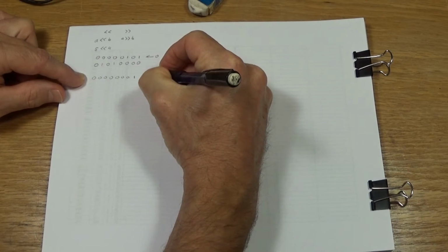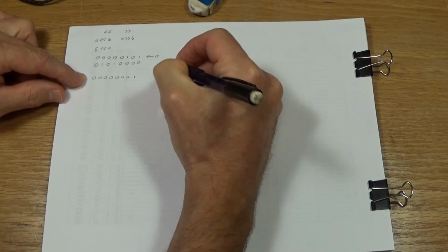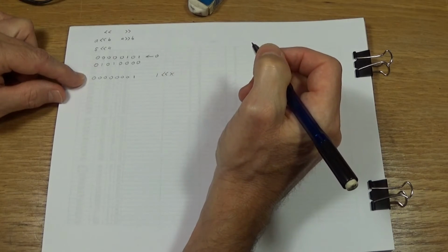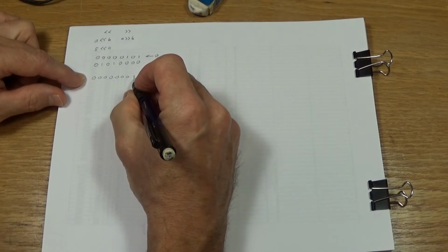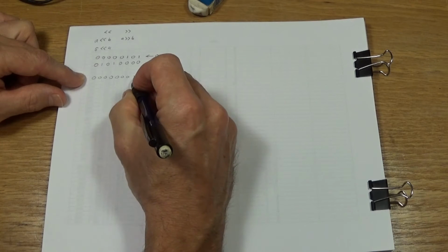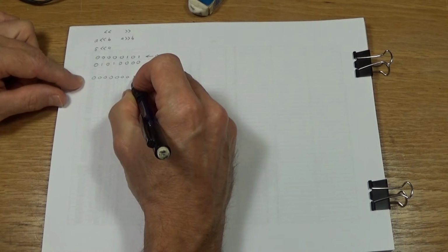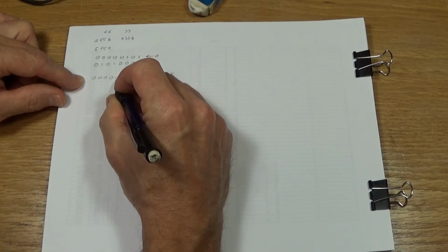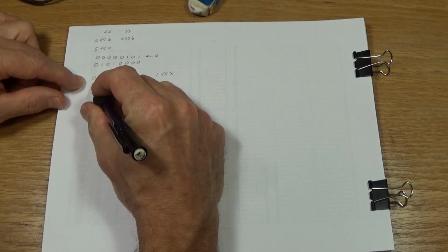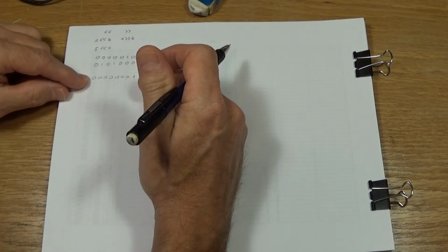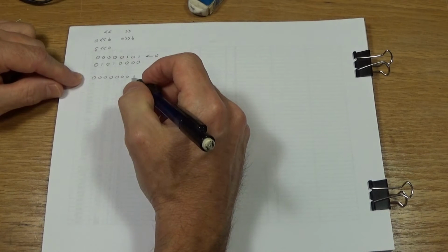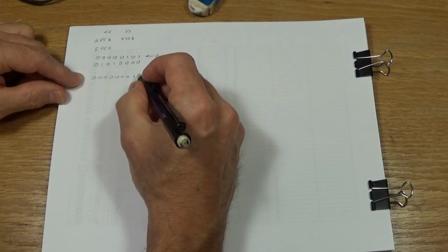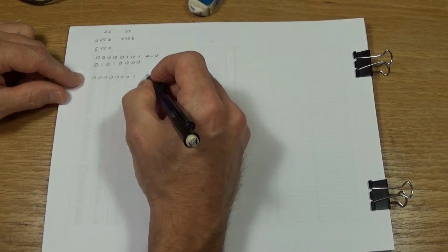So it's going to be 1 bit shifted to the left X number of times. If we bit shift it 0 times, it doesn't change. If we bit shift it 1, it moves to here, 2, 3, 4, 5, 6, and 7. And if you have a bigger number, 16 bits or whatever, you can keep going. And remember, each time that you shift it to the left, a 0 gets shifted in.